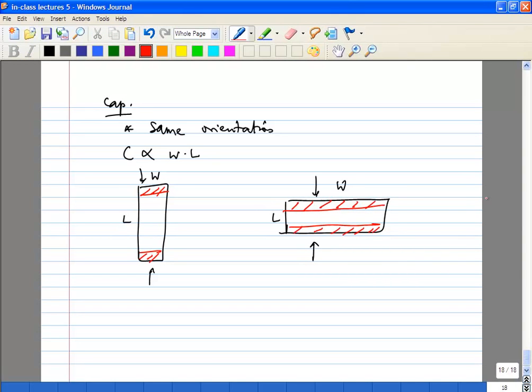Which is better? The second one is better, obviously, because you have a much wider connection, so your series resistance is much lower. So typically if you have large value capacitances where you worry about the series resistance, definitely do this. What you can do is kill a perfectly good design by doing something very bad with the capacitors. For example, I assume you guys all know about this.